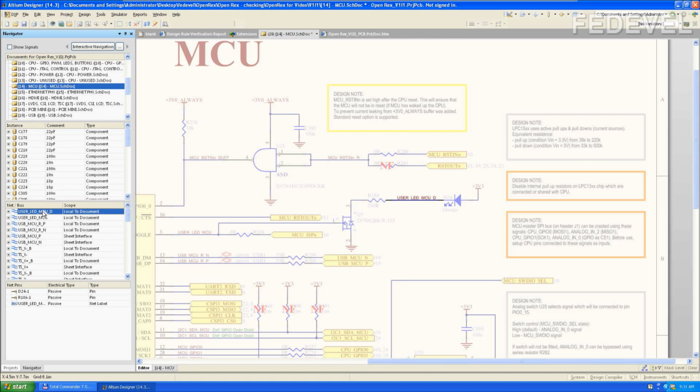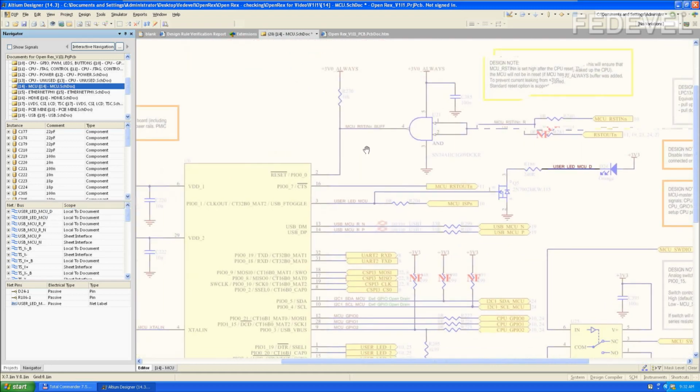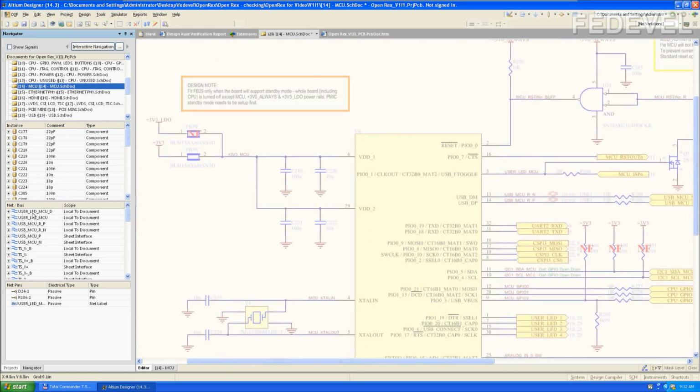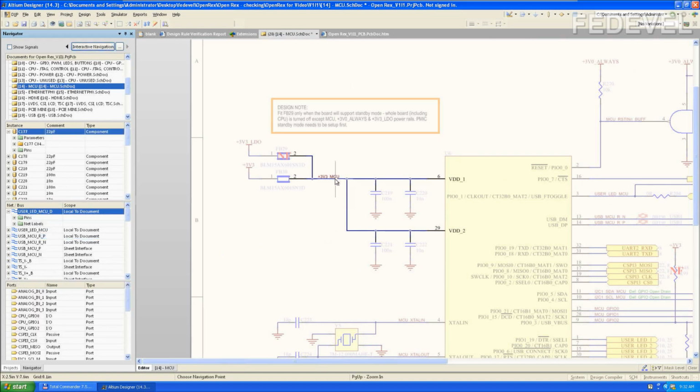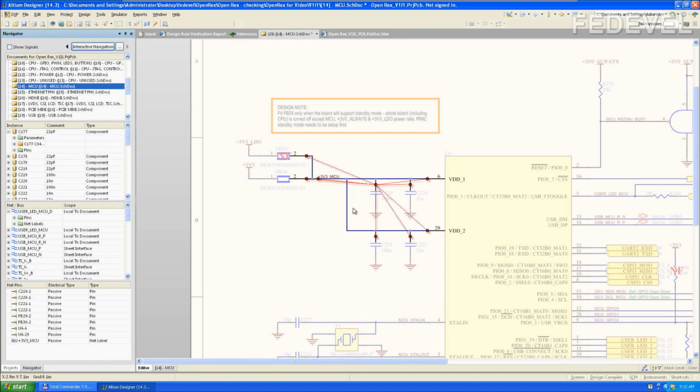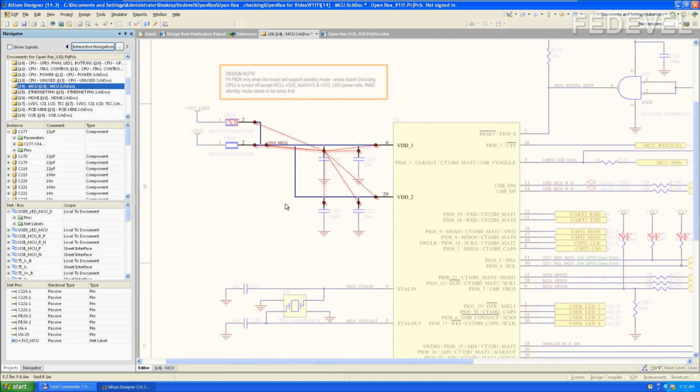What is also useful, by default Altium doesn't check this show graph. I'm going to show you what the feature is about. If I select this net, it looks like this. If I check the show graph, I checked it. When I select it now, you will see these red dots and these red lines. It's very useful. It makes the connection more visible. So I always use the show graph enabled or checked.